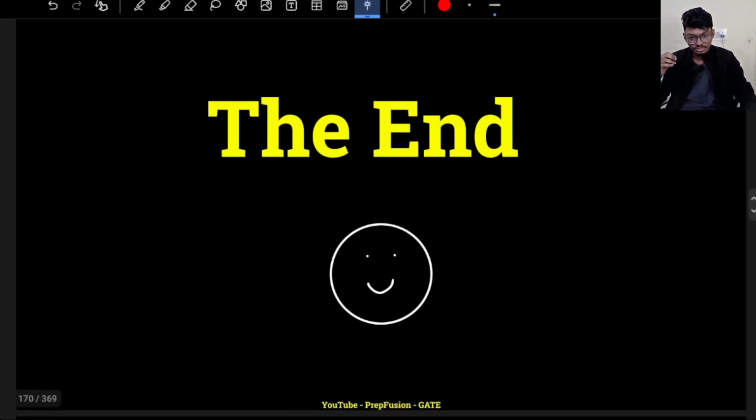In the next lecture, we'll learn a few more topics related to simulation and test bench. Up until now I've been using a test bench and simulating, but I have not explained how a test bench works or how a simulation works. I have just told you to skip it. In the next lecture, we'll learn about that and design a 4-bit ripple up counter. Also, we'll understand initial, always, and begin and end statements.